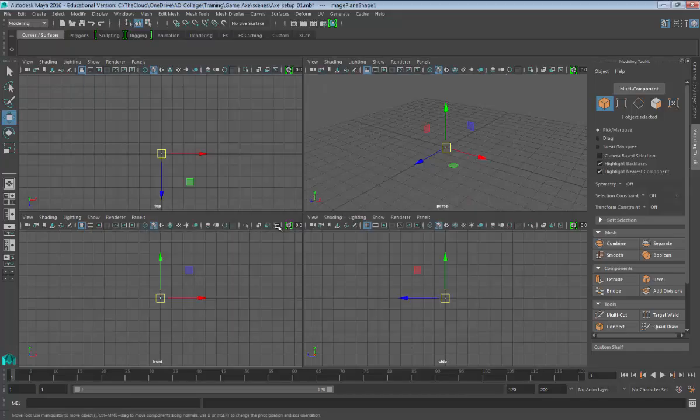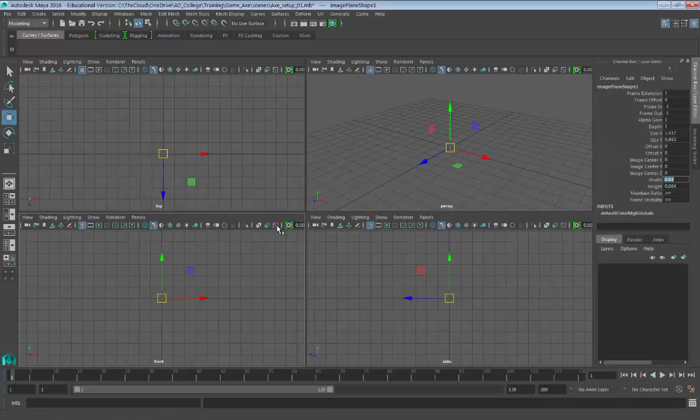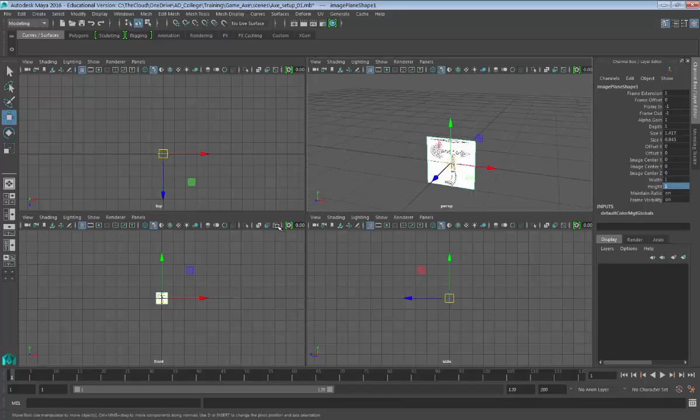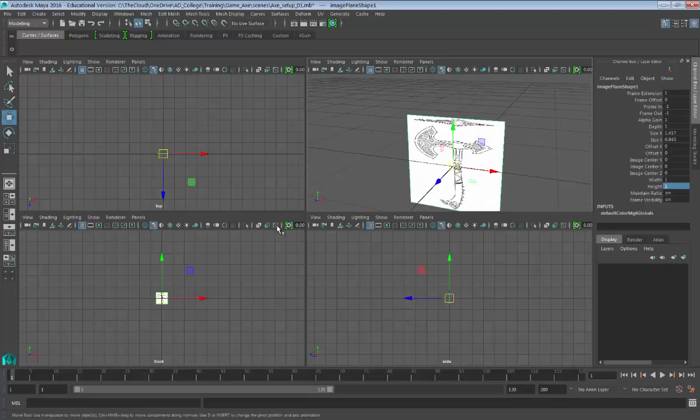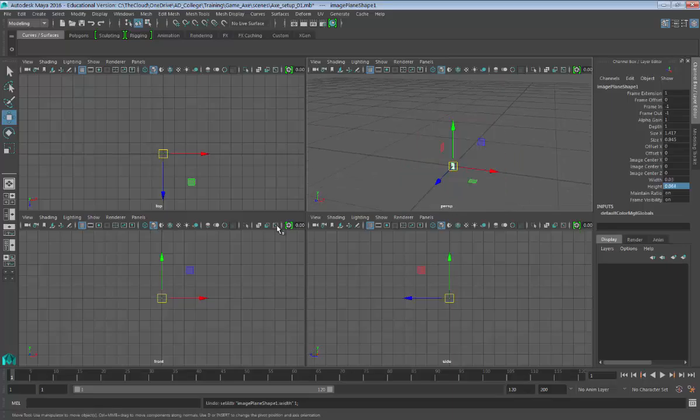And remember, because we've brought this in to centimetre scale, we need to scale it up now, so it'll have inherited those scaling options. So I'm just going to scale these up. I'm going to use 3 and 6.4 so that we retain the aspect ratios. So I'm just going to put in 3 and 6.4.